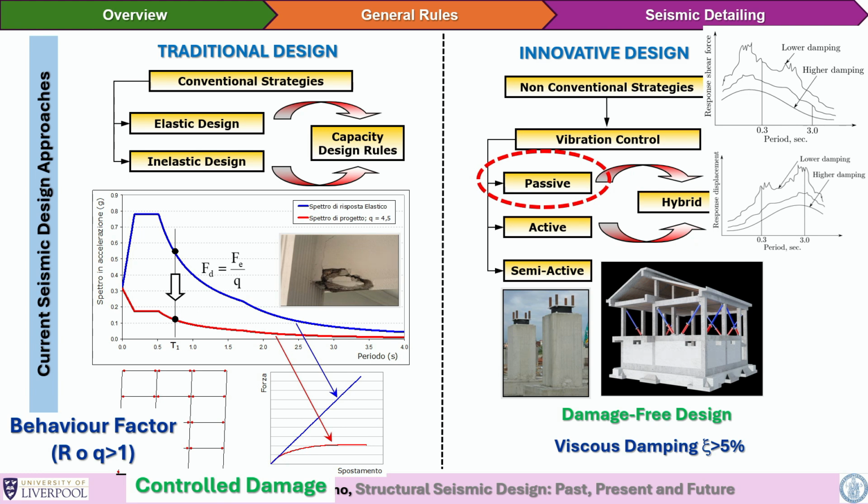This is something that is clear for engineers, not always for the client or the contractors, because they say, oh, you failed your design because after an earthquake of 6.5, which is above the 5.5 included in the code of practice, the structure failed. That's normal. I designed for that type of response to occur because I scaled down my input here. And of course, you get some damage at beam-column connections, typically observed after small and medium earthquakes, because of the weak beam, strong column approach.